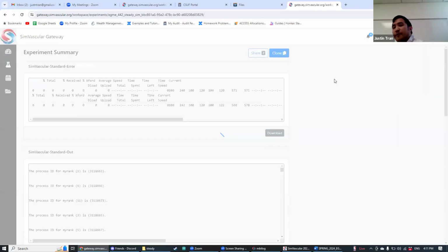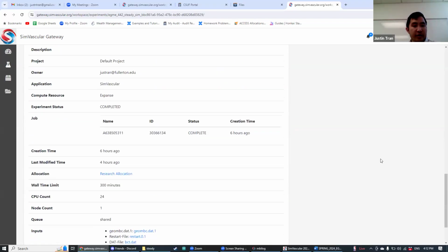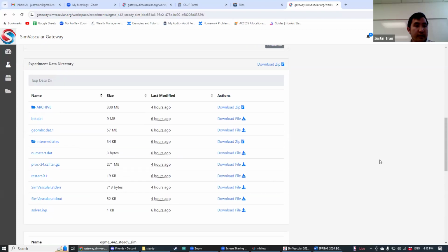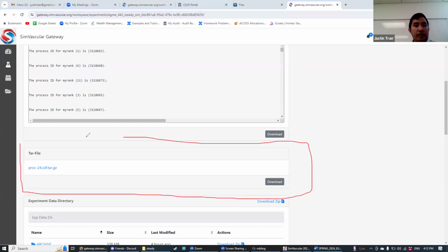Okay, so I finished the simulation earlier today. And when you finish a simulation, you'll see that there is what's called a tar file for you to download. Okay. So your tar file may be called something different. It depends on how many processors you use for your simulation. So for this particular simulation, I used 24. Okay, and so that's why it's called proc24.tar.gz. So go ahead and download this.